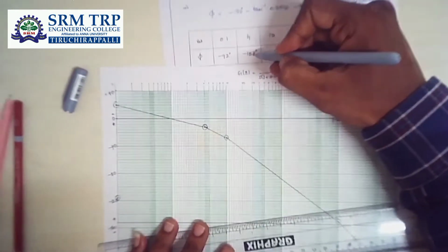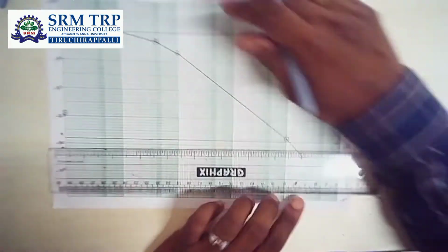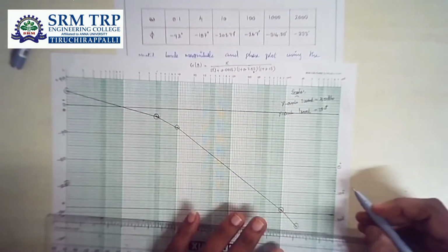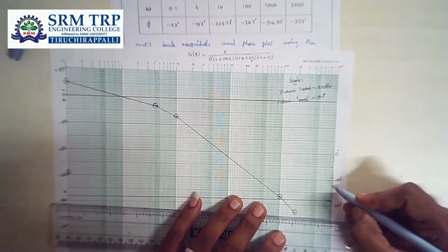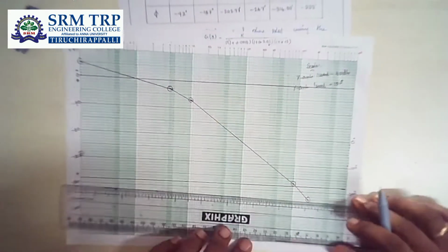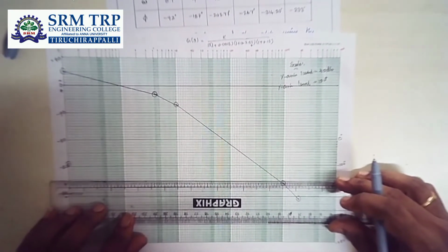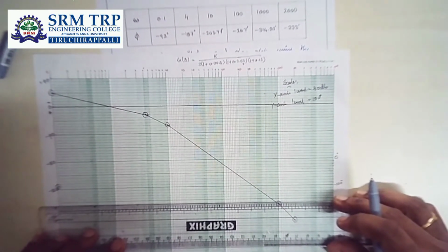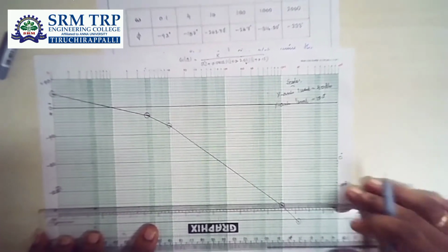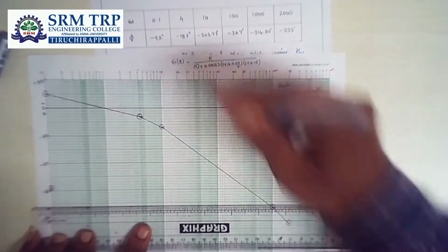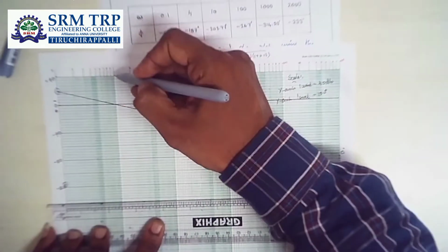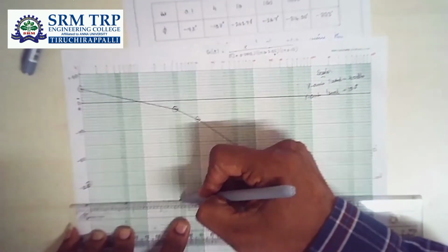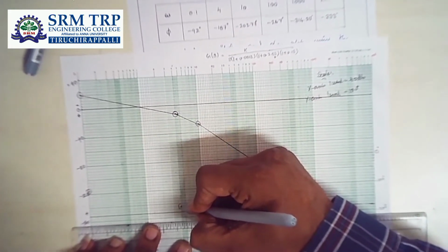Then the second one is minus 157. So I will take minus 160. Round all the values of phase angle so that it will be easy for you to place the plot. So this is minus 110, 120, 130, 140, 150, 160. So I want to keep the scale along minus 160. Placing your scale plays a vital role when you are sketching the Bode phase plot. I kept exactly at the minus 160 line. Now the corresponding frequency is 4 radian. Up to this it is 1, 2, 3. This line is 4 radian. Corresponding to this line I marked a dot and encircled it.